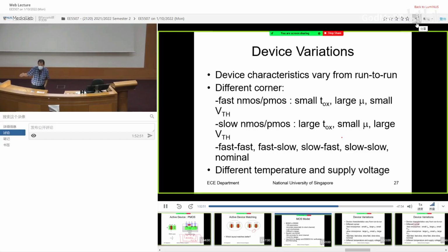And then you set some targets. The target is the offset voltage has to be smaller by how much, the gain has to be bigger by how much. These are the design specs. After you set it up, you go home and sleep. Let the program run in the background. Tomorrow you go back to the office and look at the final result, and once you see the best option, you try it again. This is a totally brute force method without any understanding. Let the computer decide for you. There are engineers doing that because they think that if the tool is so smart, why not let the tool take care of it? I'm old school. I prefer you understand what you're doing and then fine-tune.